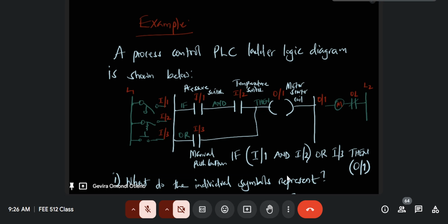So like this is a Siemens, or even if it's Allen Bradley, all their inputs are labeled I1, I2. So you'll move maybe up to I7. They usually go up to around I7. An 8-bit. So because you see you have 8 bits. So if you have an 8-bit system, you have to address them as I1. Some start from I0. Yeah, I think some start from I0 to I7 or I1 to I8, so that you have an 8-bit representation.